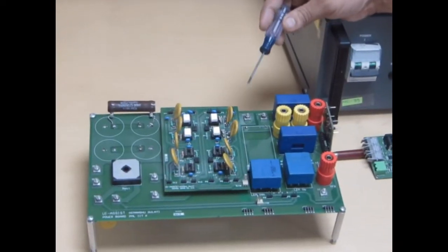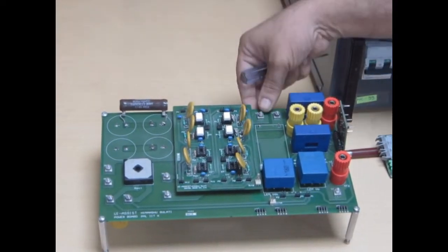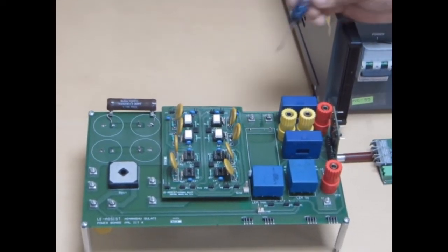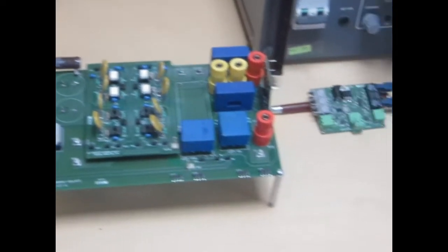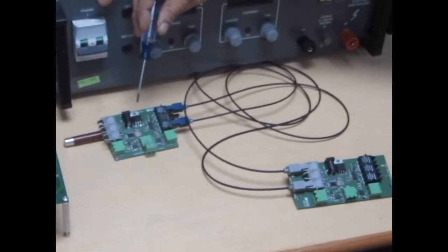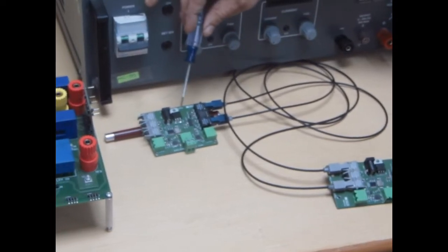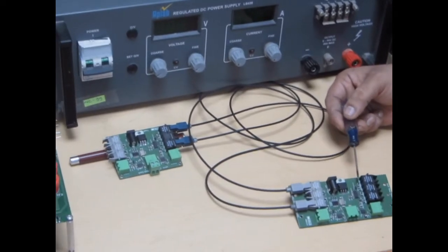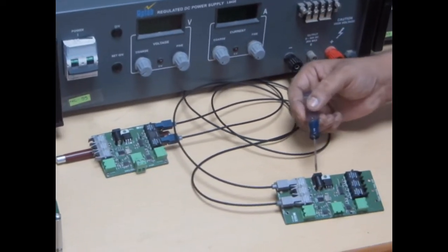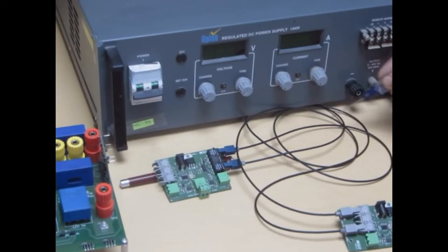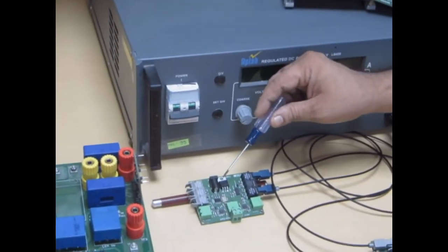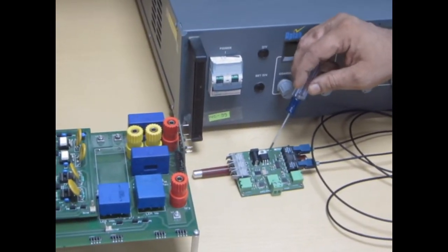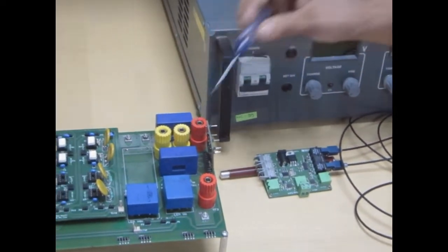This power amplifier goes between the RTDS and the smart distribution system. It is developed by our students. This power amplifier communicates with the RTDS system using these control cards. These cards are fiber optics communication and control cards. So there are two cards. One is placed close to the RTDS and it communicates with the RTDS directly, and then the information is exchanged using this fiber optics cable with another card which is placed close to the power amplifier, and this control card communicates the reference signal from the RTDS with the power amplifier.